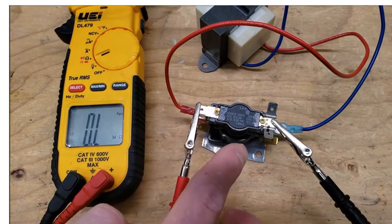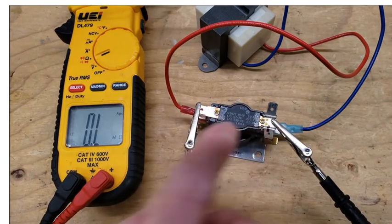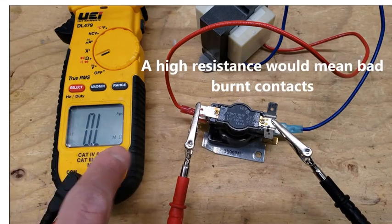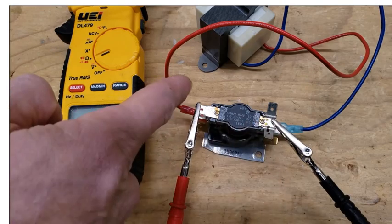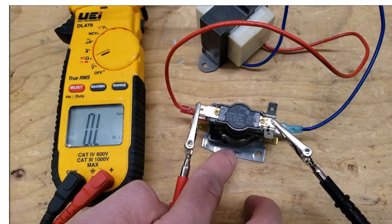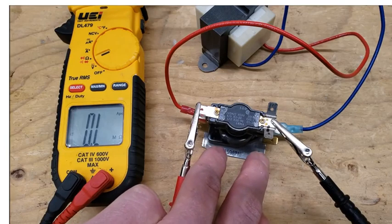So that's how you troubleshoot these. You just go ahead and apply voltage, and then make sure that when these are closed, you're reading 0.0 ohms of resistance and it's meeting the time requirement. As well, with the power off, the 24 volts off of the pane heater, you can check the resistance value of that down there. Make sure that you're not reading OL.